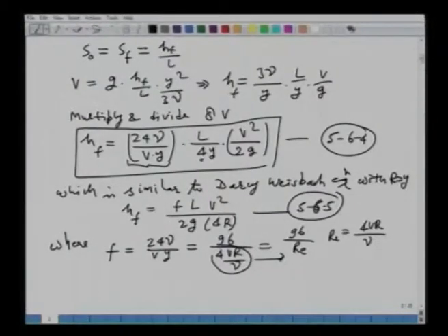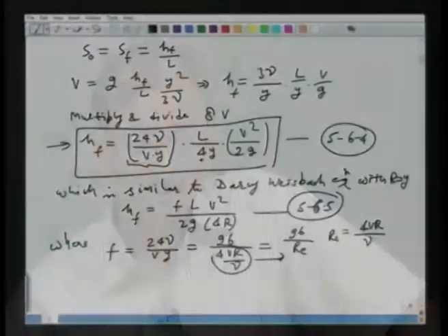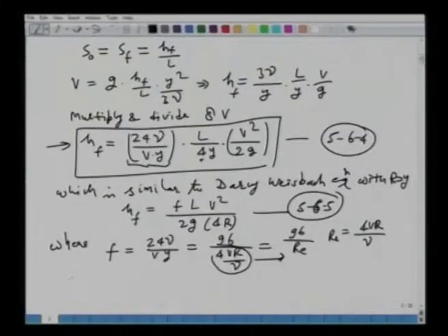Okay. So, this equation which we see here is something like the flow resistance formula, okay, in which the head loss can be calculated using a Darcy-Weisbach's equation, which is fLv squared over 2gd. Okay. This flow condition will be in the laminar region, all right. There is a certain condition in terms of the Reynolds number, we all know that. Okay. So, this will be laminar flow if the Reynolds number is less than or equal to 2000. Okay. All right.